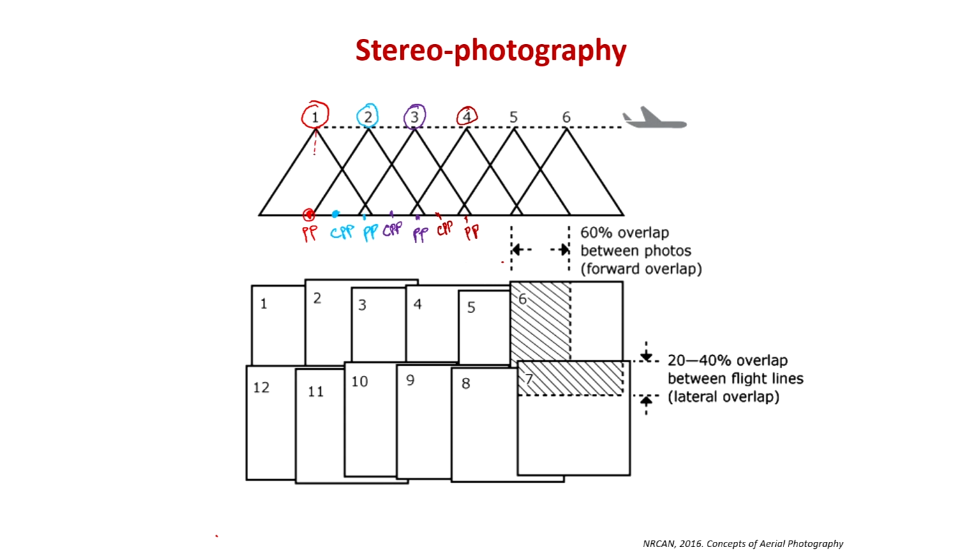You can also say that if it is exactly vertical, then this will be your nadir point, and the second photograph's principal point will be this. Okay, and respectively you will have the conjugate principal points. Okay, so this usually is helpful when the photographs have been collected and you want to do the mosaicing, and also you want to find the line of flight. Okay.